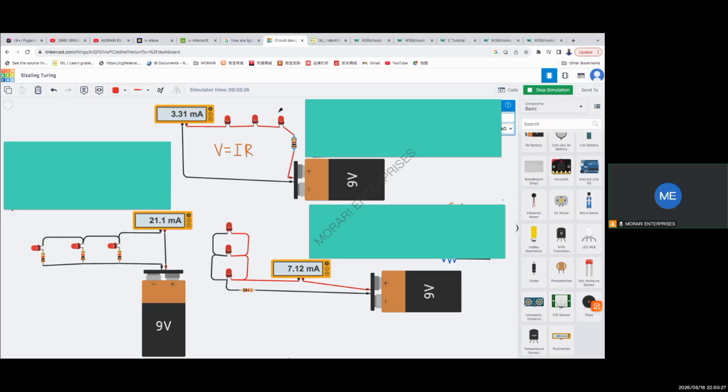And for that energy, we need to know the power that passes through the LEDs. To calculate that power, you have to ask what is the amount of electrons that are flowing through the LEDs? And what tells us the amount of electrons per second is the current intensity. And then we also need to know the voltage drop across the LED, which is that 2 volts.